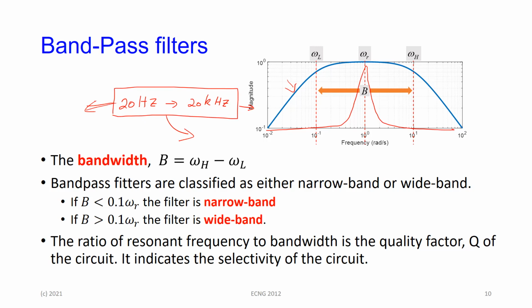The below frequencies normally would not be heard, but it could be generated by equipment noise, air conditioning noise, and the like. The high frequency noise similarly could be generated by equipment, machinery working and the like. So as not to corrupt the sound, you would pass the audio through a wideband, 20 hertz to 20 kilohertz signal filter, that would basically extract the usable part here. And this is what you're going to process for recording.